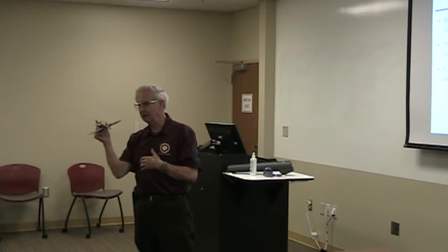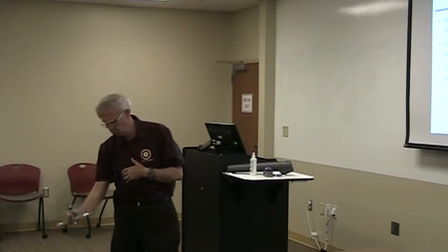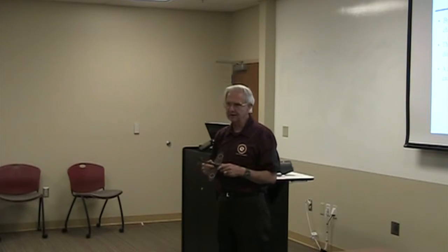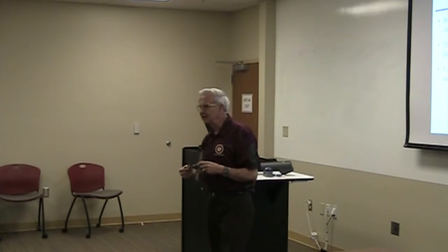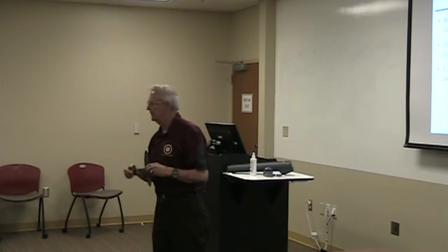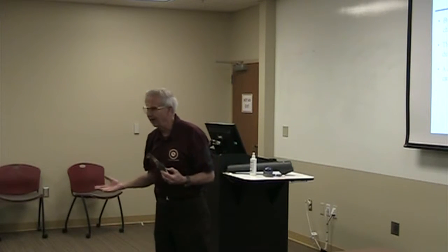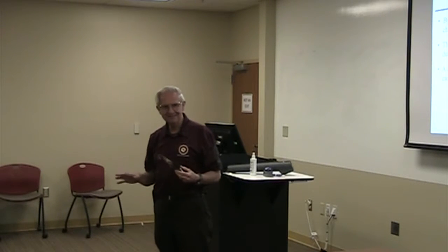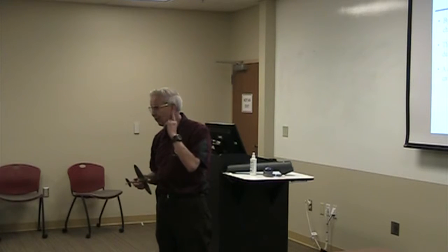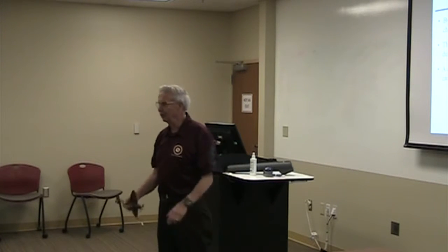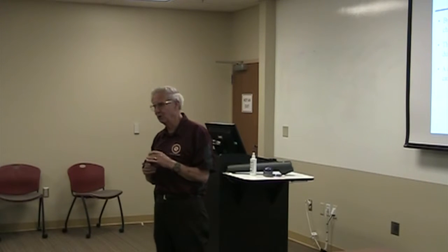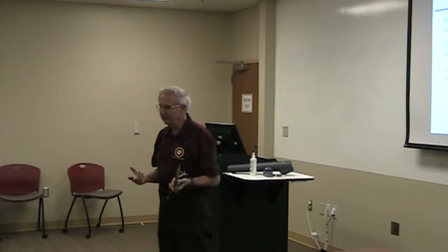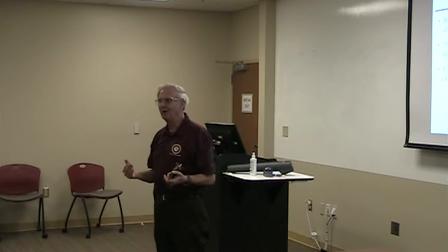Okay, so what's going to happen if you get into rudder lock? You're going to be coming down because you may not have enough power to stay up there. And particularly, rudder lock will usually occur in a single engine situation on a multi-engine airplane. Ooh, you already can't have much performance, because those of you who are in the performance course know that if you lose one engine on a multi-engine airplane, how much performance do you lose? It's a lot more than half, isn't it?